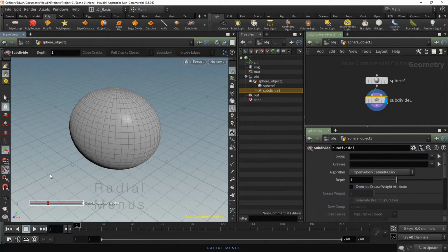By the way, similar to other 3D applications, Houdini also gives you access to the shelf tools and other functionalities directly in the viewport by using Radial Menus in the scene view. In the scene viewer, you can access these menus using the following keys: X, C, and B. The X key to access the snapping controls. You have grid, primitive, point, and multi-snapping. These are the same 4 snapping tools located in the toolbox: grid snapping, primitive snapping, point snapping, and multi-snapping.